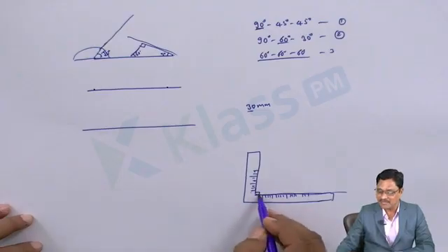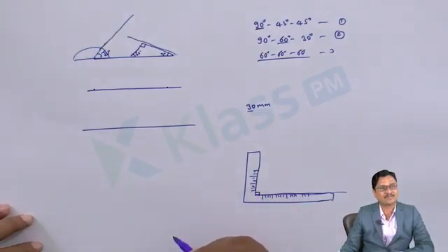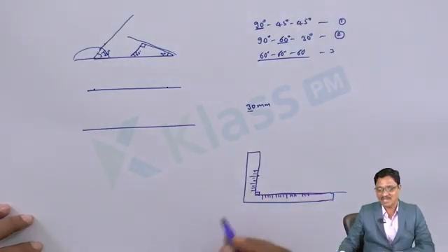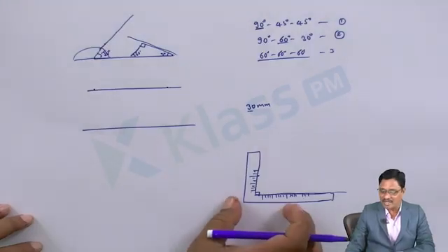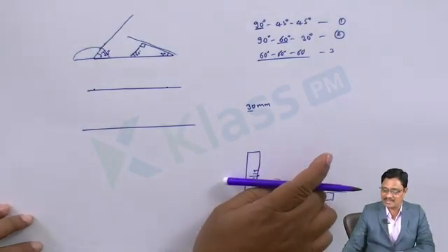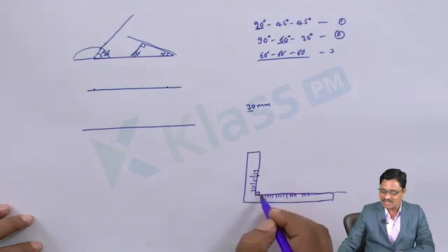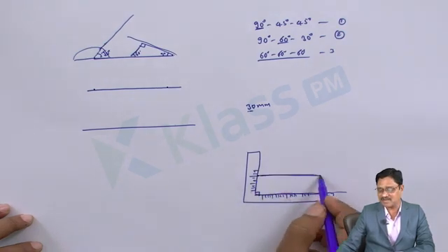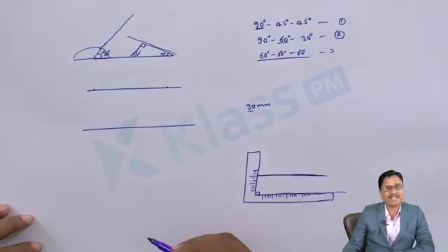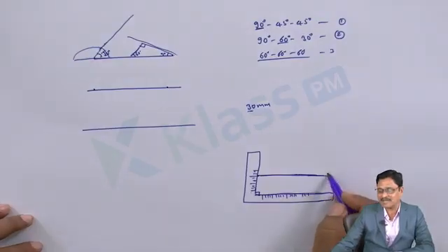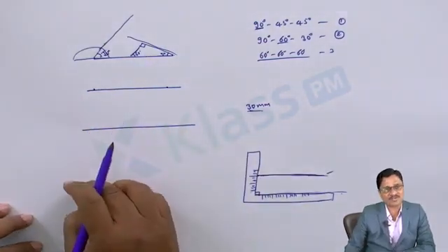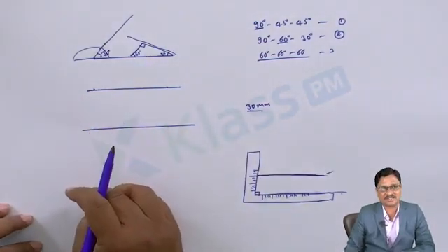So now we know that by construction, these scales are perpendicular to each other. So now I can count 1, 2, 3, at a distance of 30 mm, and I mark the reference point. Now I can move this entirely, and as the points coincide, I can draw the line with the edge reference of this. So in the very minimum time, I can get parallel lines as per our requirement. Previously, this took at least 2 minutes plus.